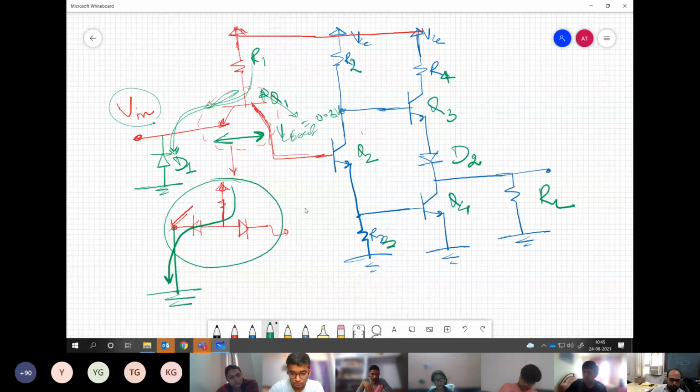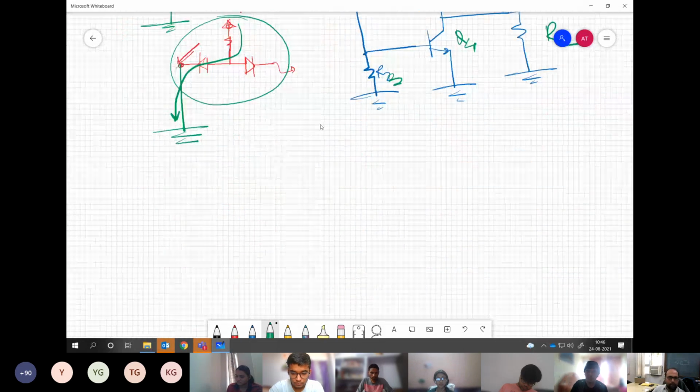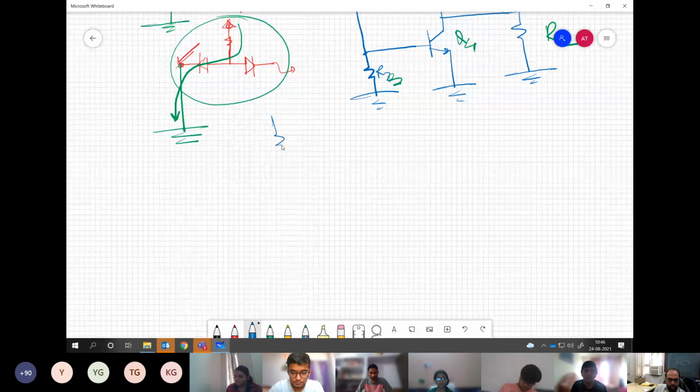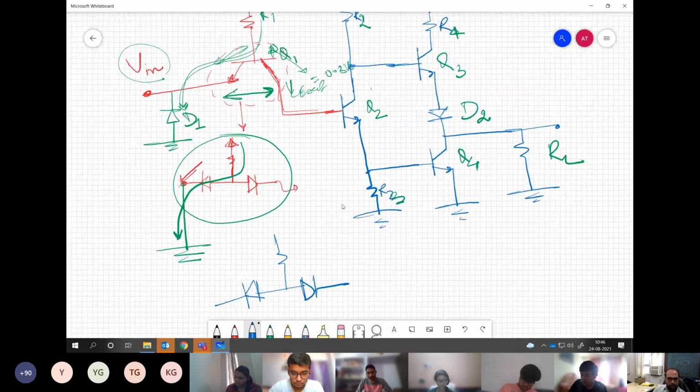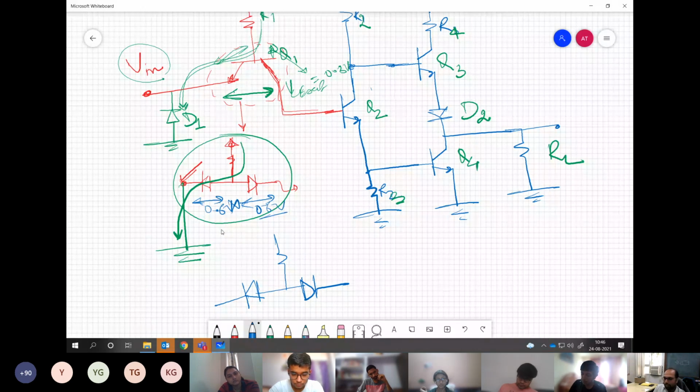Fine. Now, if we apply some high input over there, let us say, that's why I am saying for crude understanding, this is just for understanding we have put this transistor in this form. It doesn't mean that this is conducting, so you add 0.6 volt over here and then some voltage 0.6 volt over here, not like that. Finally, it is a transistor. It is only to understand how these junctions are broken, how the current is flowing, I have drawn in this configuration.